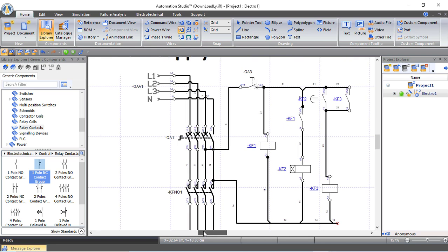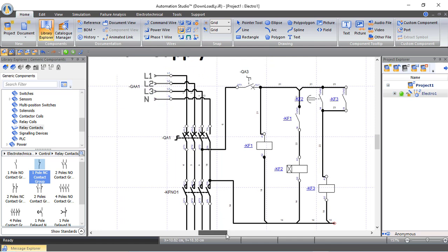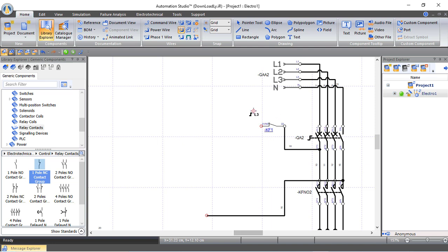So if this relay is working, which means that there is a main power source here, it will open the circuit for the control circuit of the generator. We don't want this generator to be working. Perfect. Now let's bring this line wire and let's create our control circuit for this generator or backup circuit.